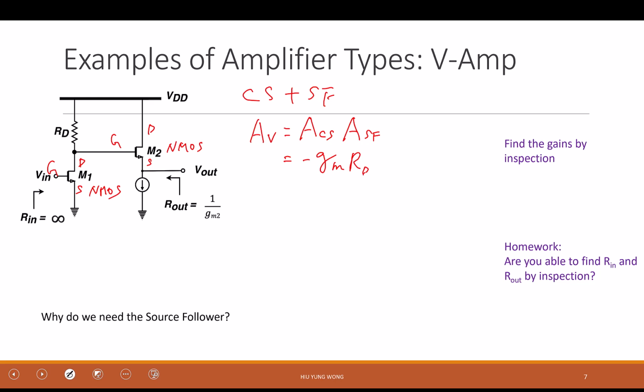What is the gain of the source follower in the first order or 0th order of approximation, right? You can forget all the complicated equations, but if you go to an interview, people ask you, what is the gain of a source follower? You better say, it is 1. No use, it is 1. Yeah. Although it's gm ro divided by 1 plus gm ro, then you can continue.